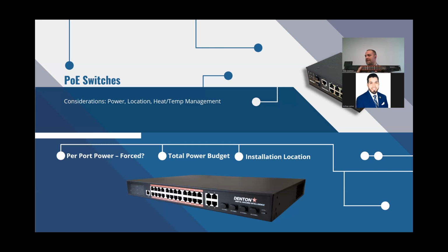And what that means is, and we'll go through this in the planning, you'll want to make sure that you're picking your equipment based on the total power budget you need. Now, I can tell you for PoE Texas, this guy is designed for 2,160 watts of power. It will do 90 watts per port, all 24 ports with our power supply.